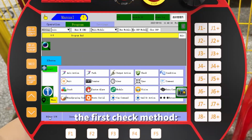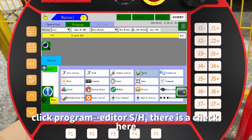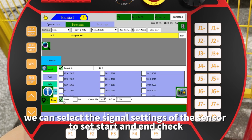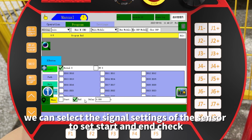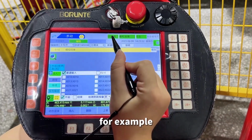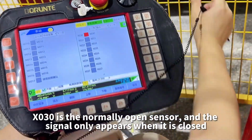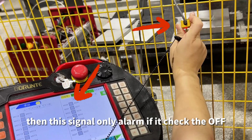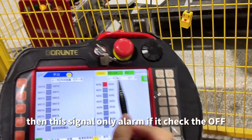For the first method, click Program, Editor, there is a check here. We can select the signal settings of the sensor to set start, and then check robot alarms when it detects an ON or OFF signal, and delay, to complete the continuous signal check. For example, X030 is a normally open sensor, and the signal only appears when it is closed. Then this signal only alarms if it is checked as OFF.